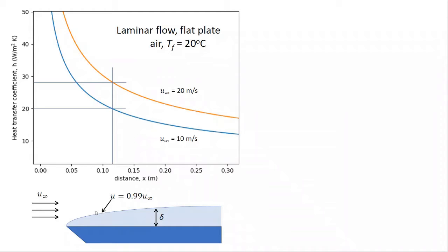But we know they're proportional to each other, and as the velocity boundary layer thickens, so does the thermal boundary layer. So this thicker boundary layer, as we move further from the leading edge, results in a lower temperature gradient. It's resulting in a lower velocity gradient, which corresponds to smaller shear stress at the surface farther away from the leading edge.